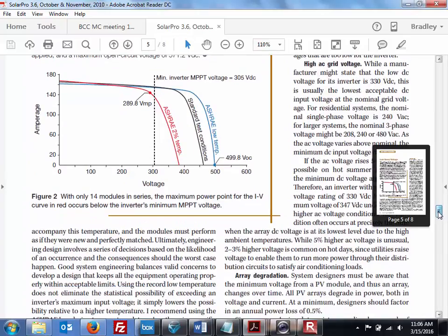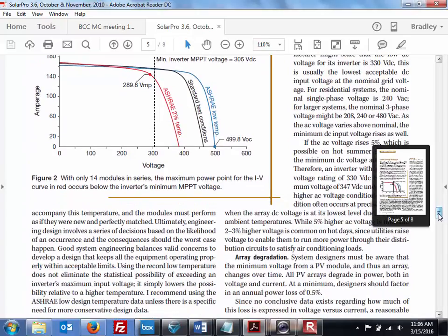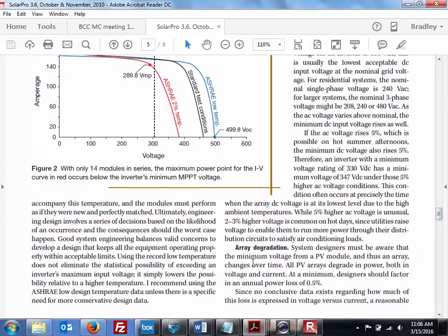Another thing to consider is that panels will lose performance over time, and they're typically rated that they're going to lose 1% per year. So you have to take that into account over the lifetime of the panels. No technology lasts forever, and it's not going to be linear either, but they're almost always listed with a sort of percentage loss of function per year. Is that just materials degradation, basically?